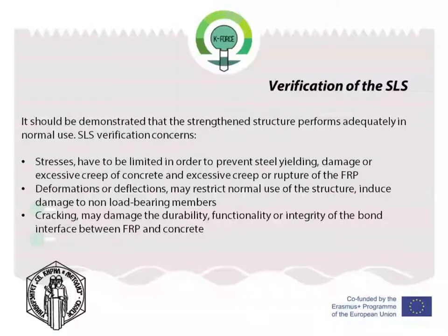It should be demonstrated that the strengthened structure performs adequately in normal use. To meet these requirements, the serviceability limit state verification concerns stresses, which have to be limited in order to prevent steel yielding, damage or excessive creep of concrete, and excessive creep or creep rupture of the FRP.